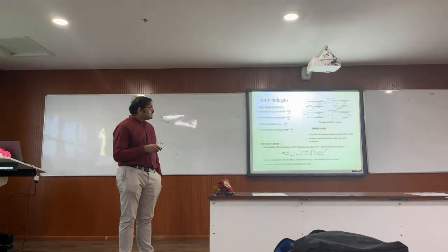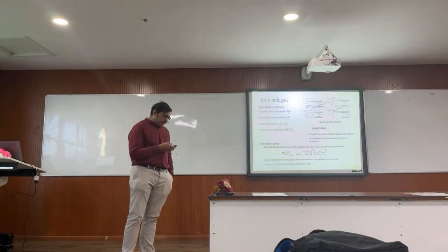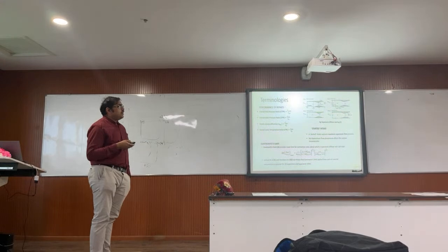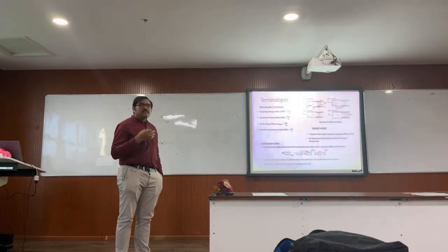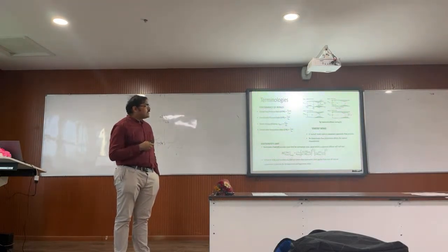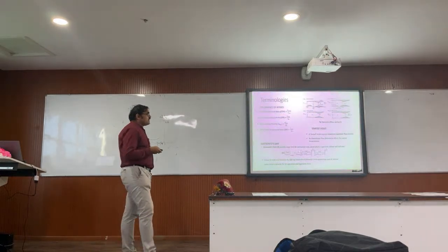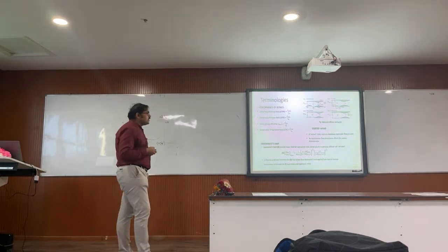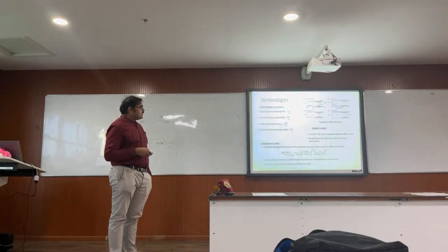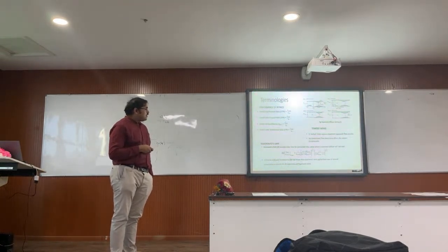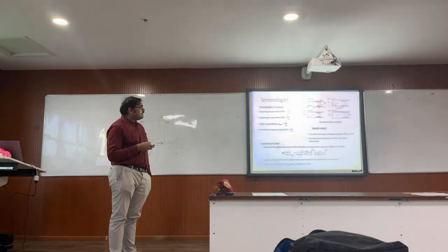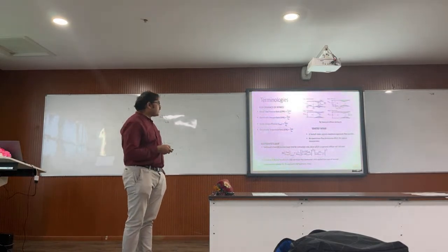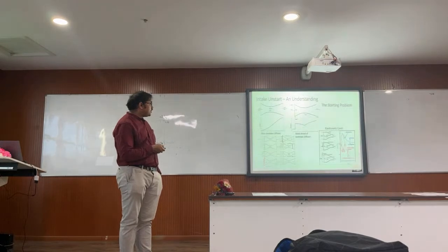This is a started intake, but these intakes can get unstarted very easily because the flight can go into off-design conditions, or you may happen to throttle the combustion chamber and then suddenly the back pressure, the pressure after the intake, may increase because of such throttling phenomena, and then it can cause certain phenomena to occur by which the intake goes to unstart. And a very conservative limit, this is from a geometry perspective, tells what the minimum area at this diffuser should be such that the intake always starts. It is given by the Kantrowitz limit, and I will explain to you why that comes about.